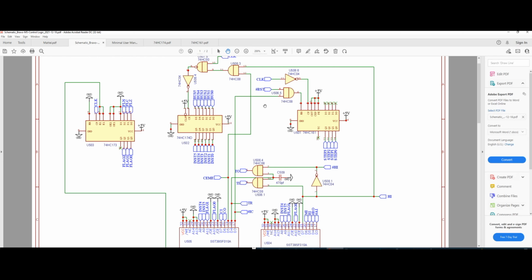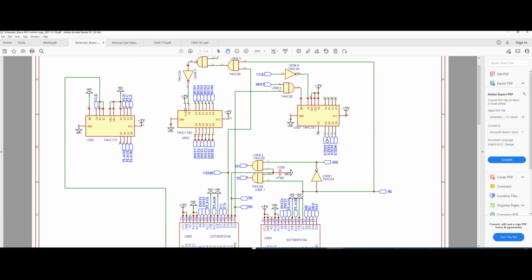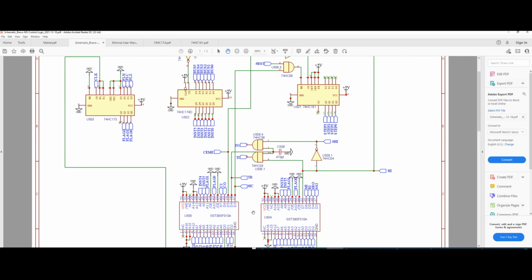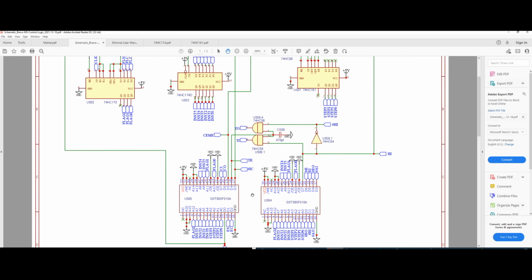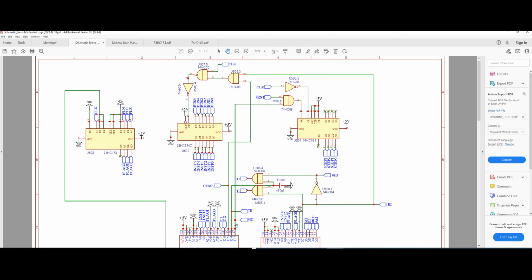So the idea here is to pulse the clock, and each time we pulse the clock, this microstep counter will be counting, and it's outputting a different address on the output lines. The combination of this address and the output of the instruction register and the flag will be addressing a different location on the RAM. And obviously we specified through our microcode, or test microcode, that with each microstep one signal will be outputted from those chips.